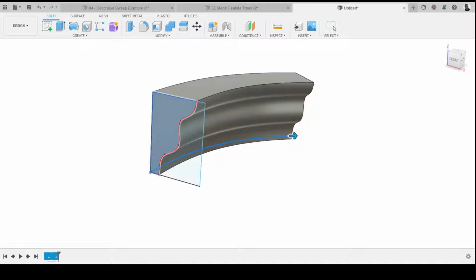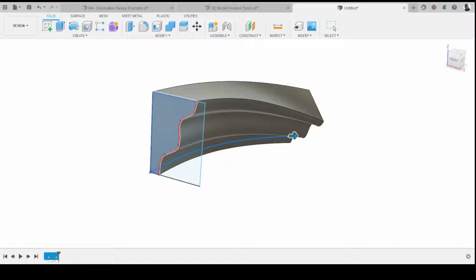You can also twist things along the path, which is a really handy thing. And in the next example, we'll see that in more detail. But if you want something to twist along the path, you can twist it by degrees, minus degrees. It'll twist how you want. So you can do quite complex shapes quite quickly. But it's quite specific in the kind of things you might want to do. In my experience, as you just said, sometimes putting edges for routing on rebates on edges of curved things, it's really useful for.